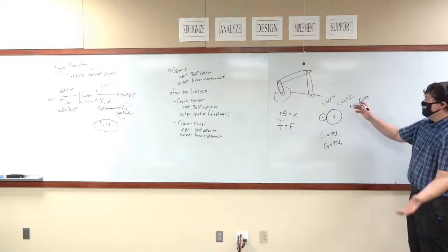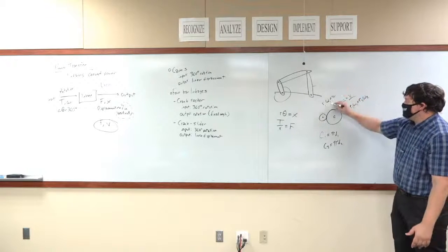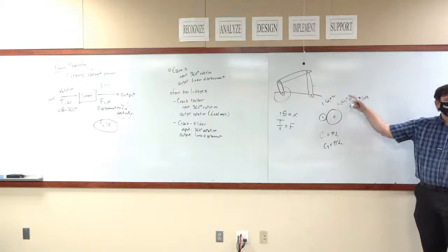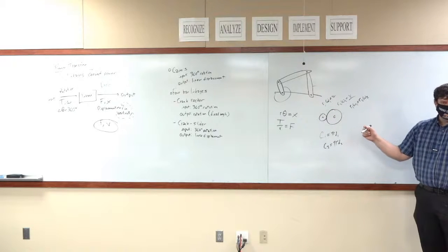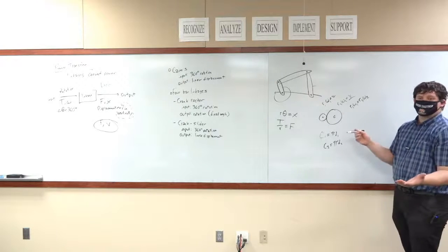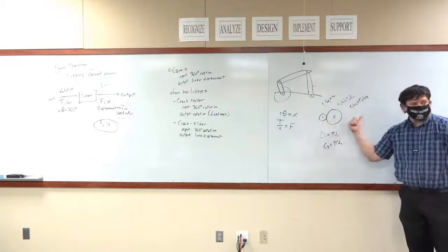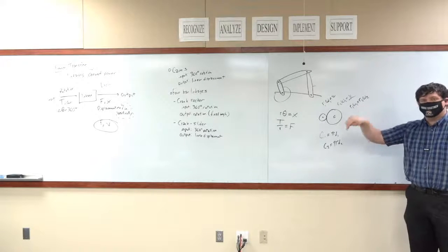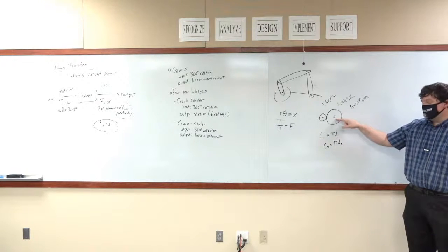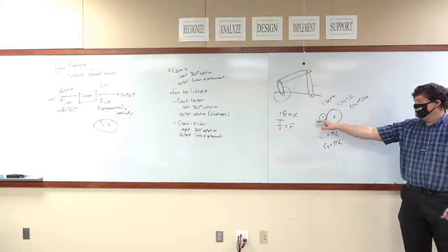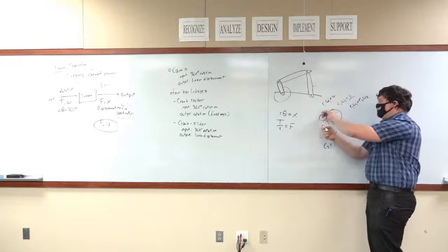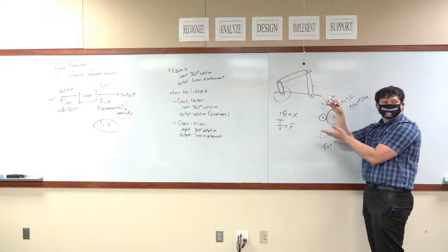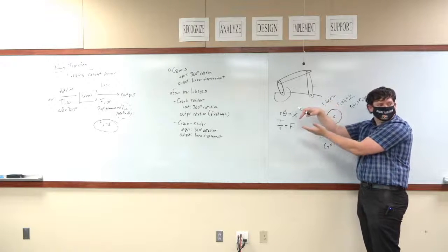Comparing the angular speeds here, the connection between them changes. So the simple thing is, if you want something to go faster, you just gear it up. Or gear it down, sorry. You start at a larger gear, you go to a smaller gear. And then maybe you'll have a gear shaft that comes out like this, and then you go to another larger gear, and then that meshes with a smaller gear.